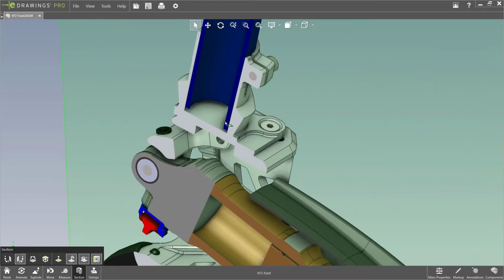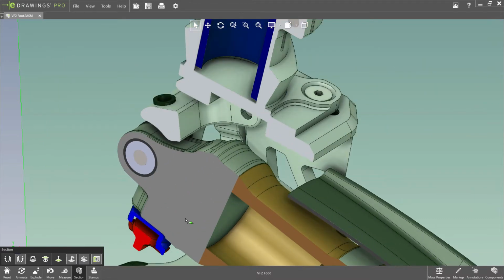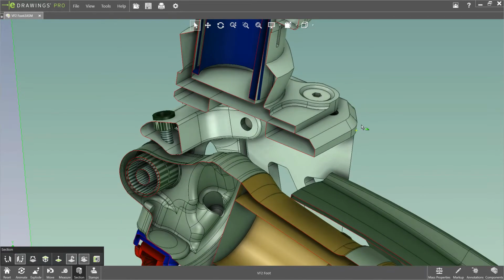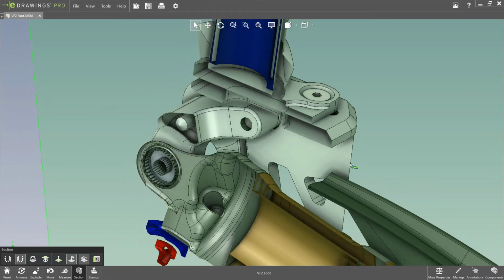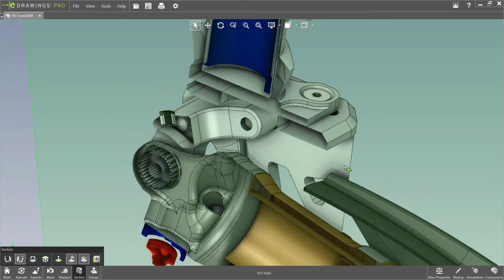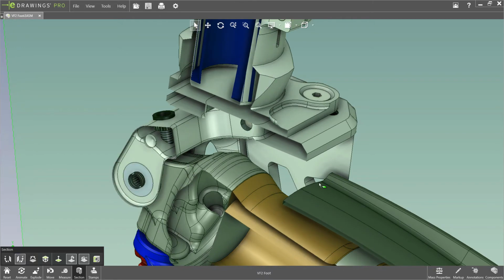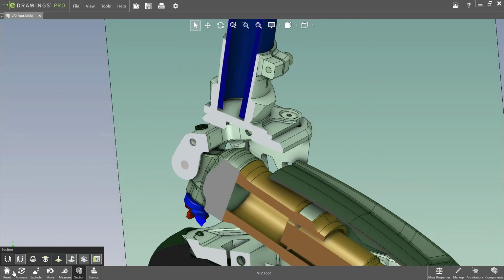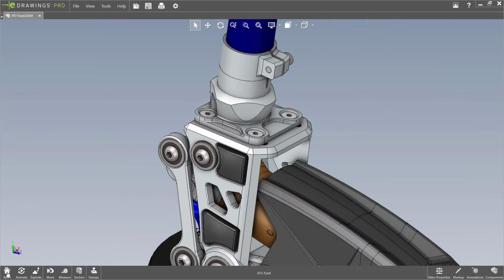So you'll notice if I zoom in here, what would be the sectioned faces in the real world, there'd be some solid material there. If we wanted to just see through the skin of the model, we can choose to deselect the cap. It often gives a little bit more of a complicated view, I guess, but useful for seeing inside the part. Again, to return to normal, we can either deselect section or press the home button.